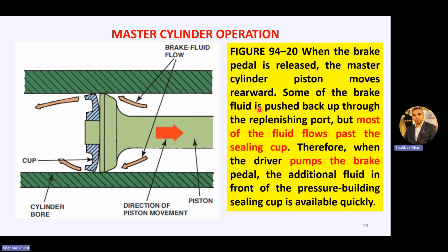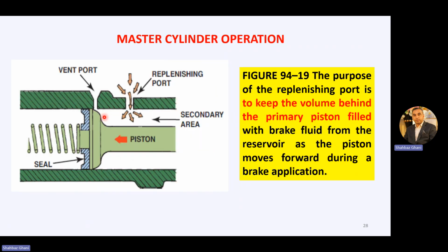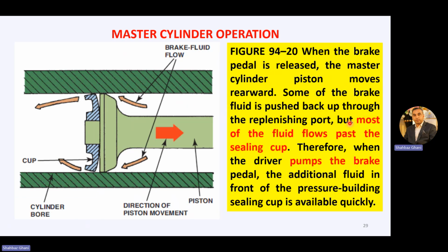Some of the brake fluid is pushed back up through the replenishing port. But most of the fluid flows past this piston surface and this sealing cup.